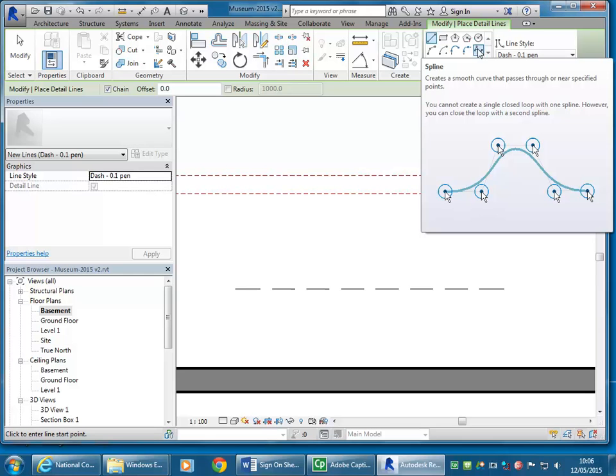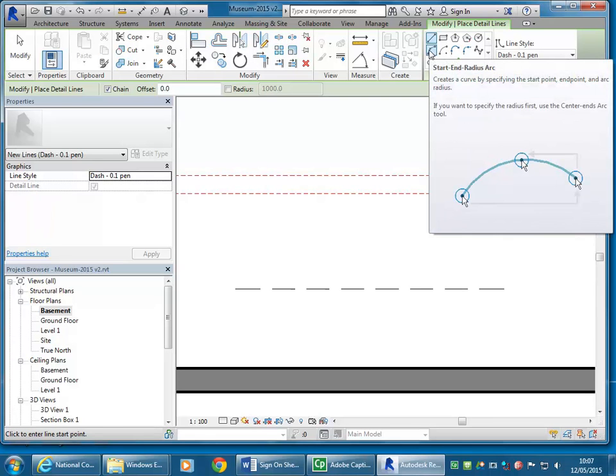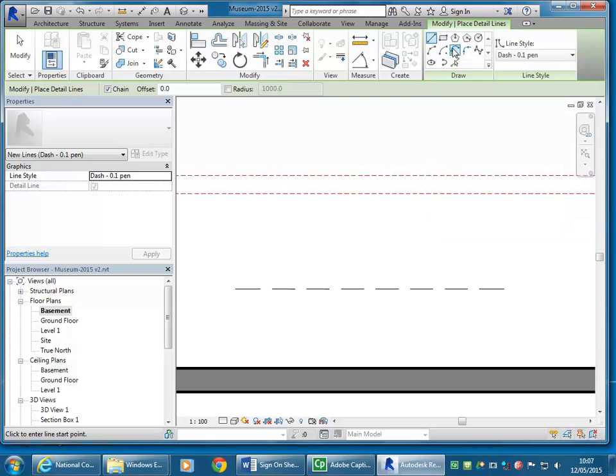If you really want to do one, what I'd recommend is that you do it in AutoCAD first. It's much easier to work out the lines that way and then bring those lines into Revit. But honestly, the best option is to try and do what you want using arcs instead. So arcs, being a segment of a circle, are much easier to divide up and work with generally.